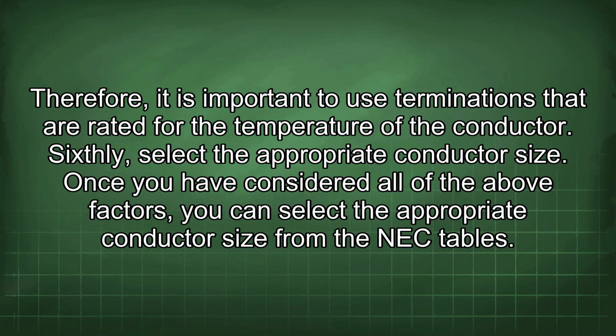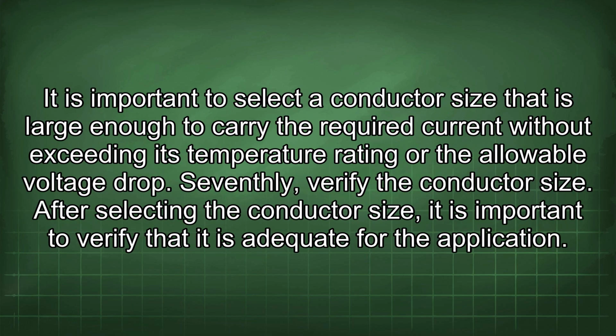Sixthly, select the appropriate conductor size. Once you have considered all of the above factors, you can select the appropriate conductor size from the NEC tables. It is important to select a conductor size that is large enough to carry the required current without exceeding its temperature rating or the allowable voltage drop.